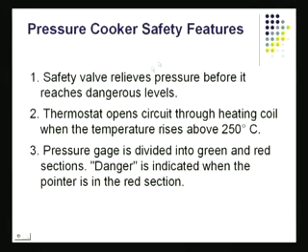This is its function. These are the safety functions. It could fail because, if the safety valve does not release, that could lead to a major explosion. The thermostat opens the circuit through a coil before the temperature rises above 250 Celsius, and this also is a dangerous situation. So the safety valve could fail, or the thermostat could fail, or the pressure gauge